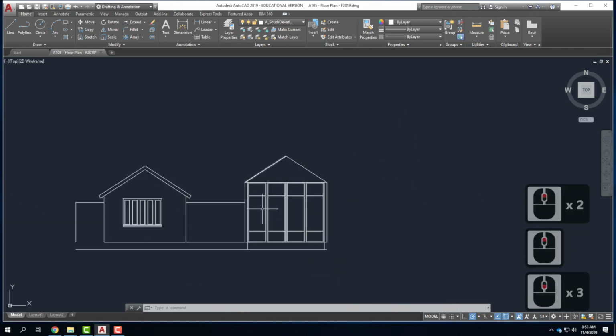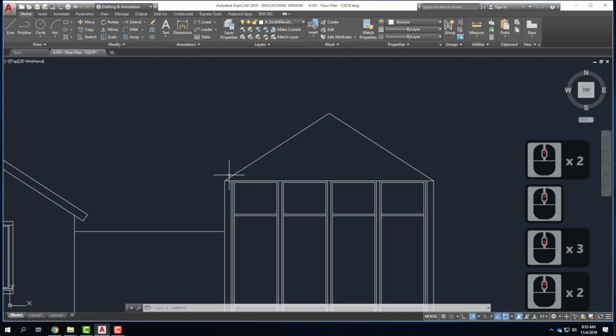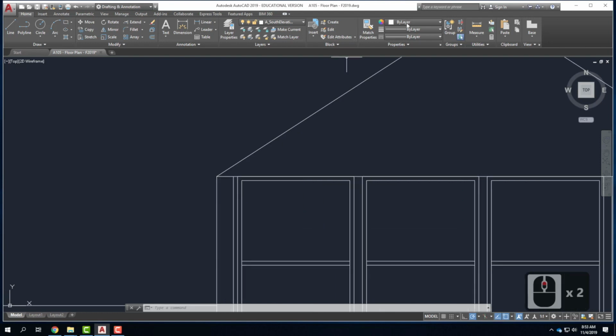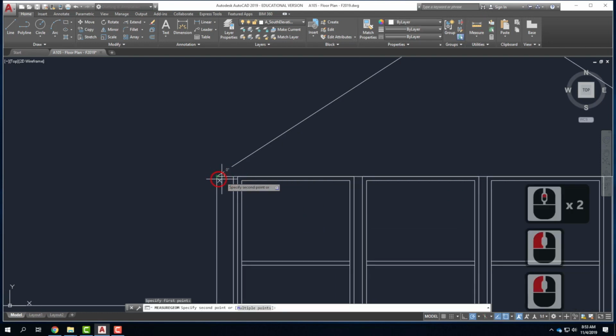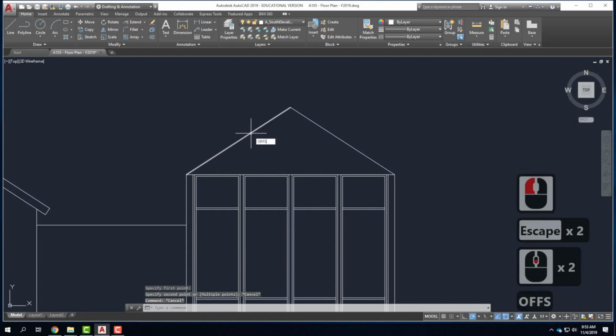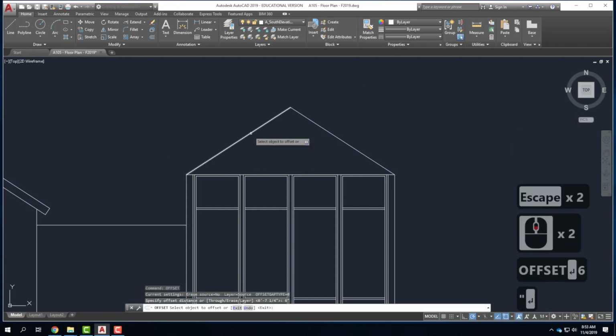So in this case, it's set up a little bit differently. I have kind of like a wing wall that's sticking out toward us. I'm going to transition that over into the roof itself. That's at 6 inches, I believe. Let me double check what it is. Yep, it's at 6 inches. So I'm going to do the same thing on the roof. So I'm going to offset by 6 inches.